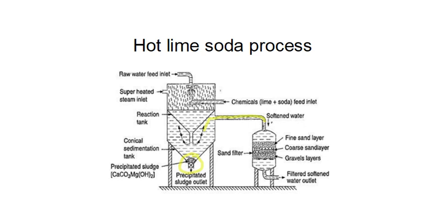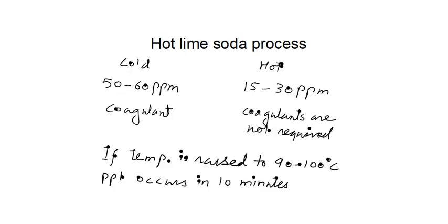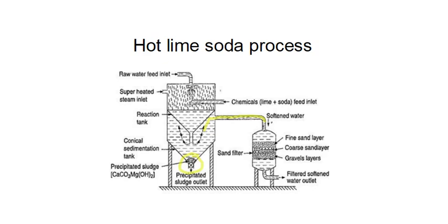What maximum can be achieved is that the raw water which is filtered and having significant hardness can be treated with lime and soda to reduce the hardness up to 90%, 95%. Say the hardness of water, if it is in the range of 300 to 500 ppm, can be brought down to 50 ppm.